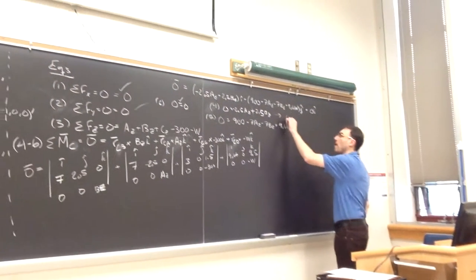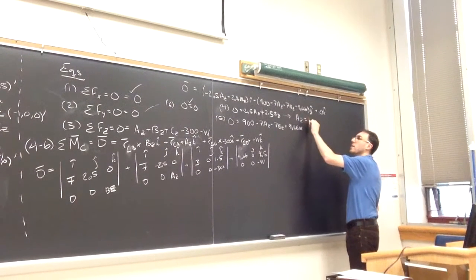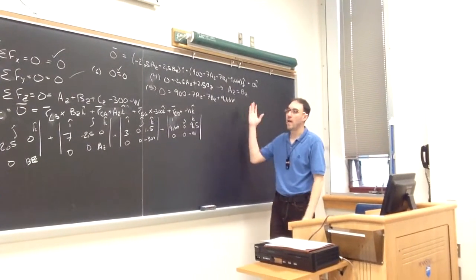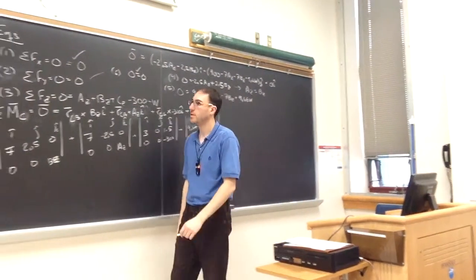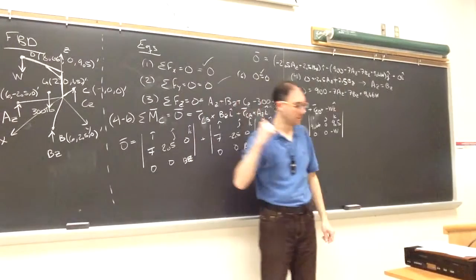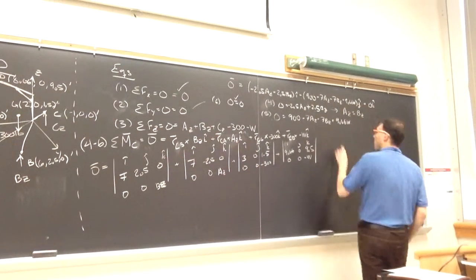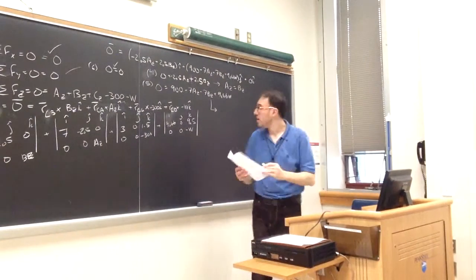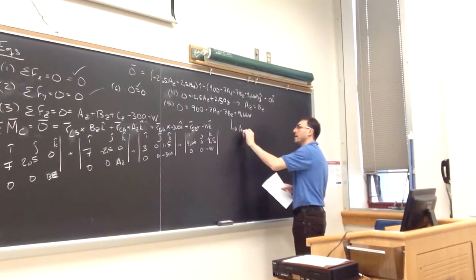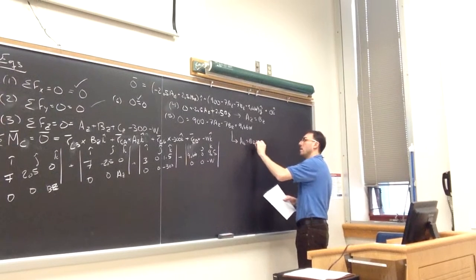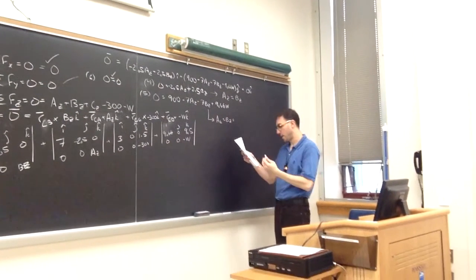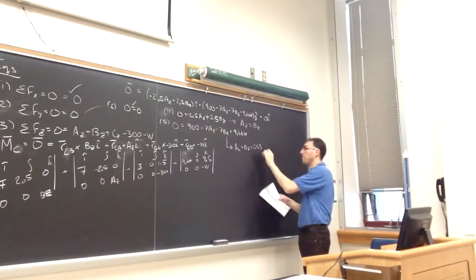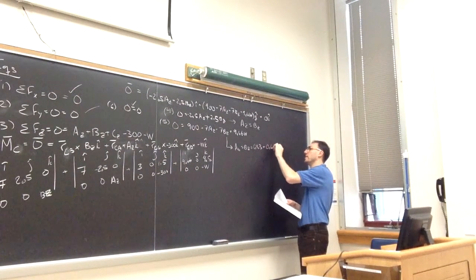Right, this is where it is symmetric. So using equation 4, AZ and BZ are equal to each other. If we had assumed symmetry up front, we would have gotten that same result. And if I rearrange equation 5 a little bit, algebraically, I get that AZ and BZ, since they're the same, are both equal to 64.3 plus 0.69 W.